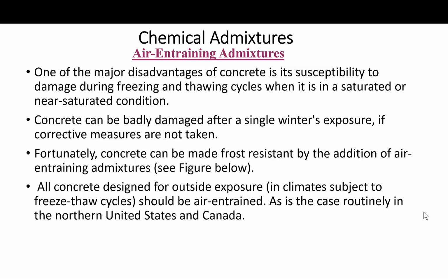Fortunately for us, concrete can be made frost resistant by the addition of air-entraining admixtures, as we will see in the next slide. All concrete designed for outside exposure should be air-entrained routinely in the northern United States and throughout Canada.